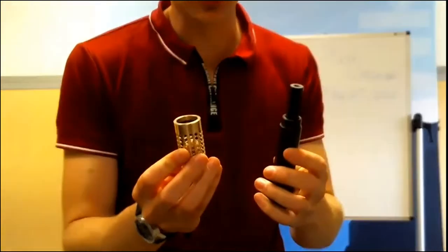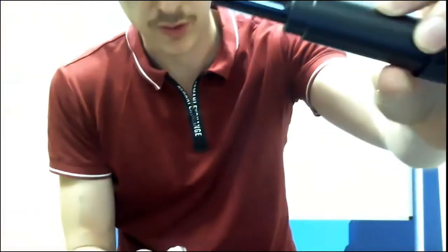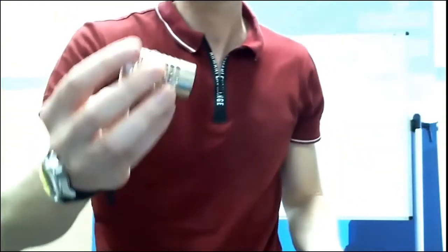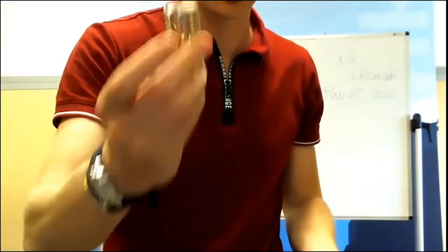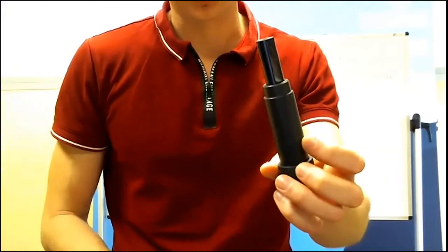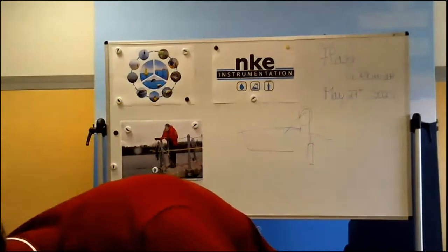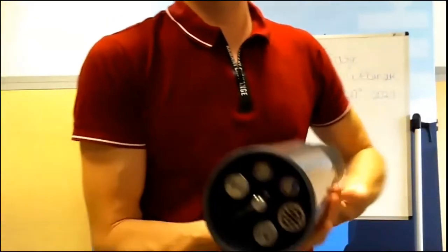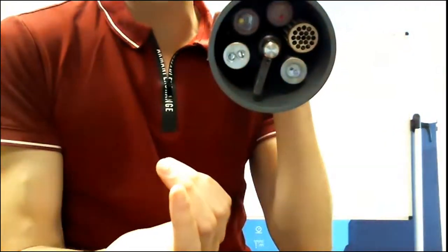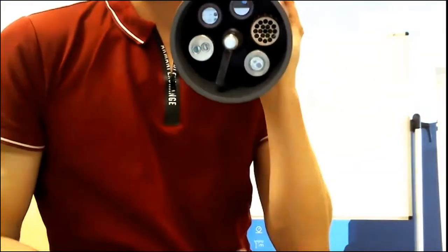So it means that for maintenance, you remove the copper cage and you can clean the CT sensor. You can see here the conductivity and temperature cells. You remove this, you can clean this with a metallic brush, and then you clean this CT cell with fresh water. And for the other ones, the optical sensors are cleaned by the digital wiper. The wiper, on a determined sequence, will be cleaning the optical sensor to optimize fouling.